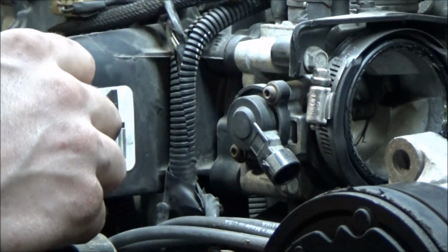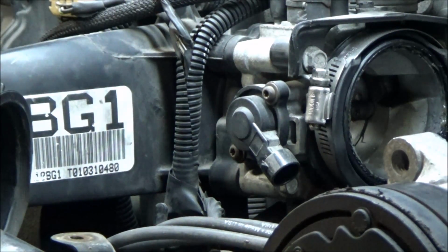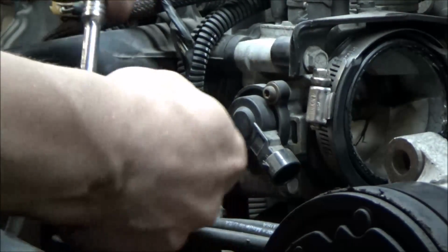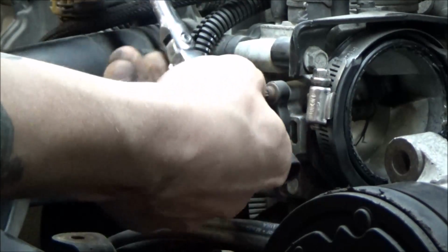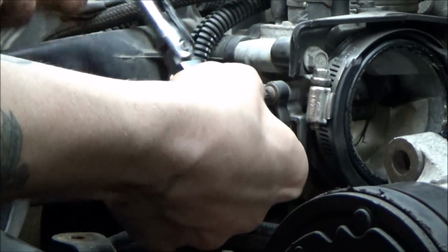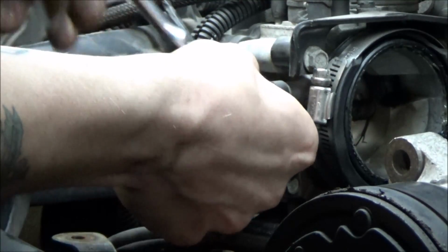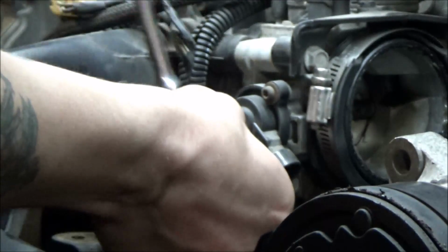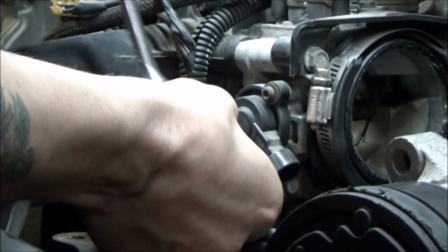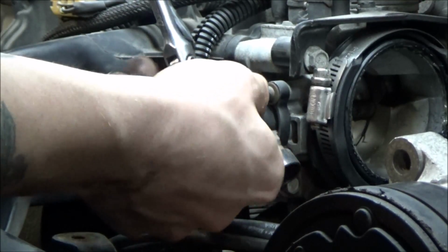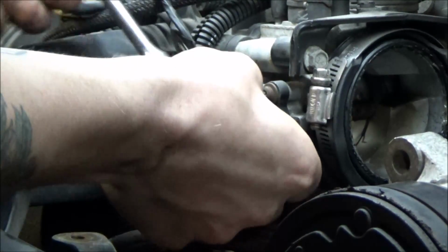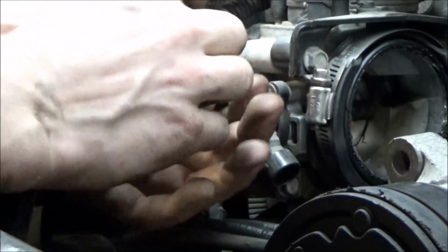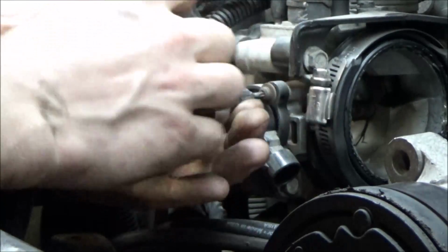So this unit's held on here by 2 T20 screws. So I've just got a ratchet here, and I'm just going to get this thing broken loose and off of this thing real quick. These fasteners are not very tight, guys. They also do not need to be reinstalled tight. So just pulling these screws out of here. Obviously, in order to replace this unit, guys, you would need to pull that air box out so you can get a ratchet in here and do this. But obviously we already did that during the testing process on this thing.